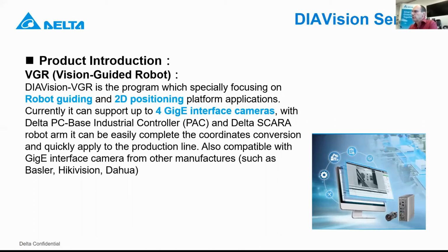The camera is based on GigE in that case. Our industrial cameras can be used, but they are at this moment only available with Power over Ethernet. So you need a special card in the industrial PC, or you need an injector to create the power over the Ethernet.